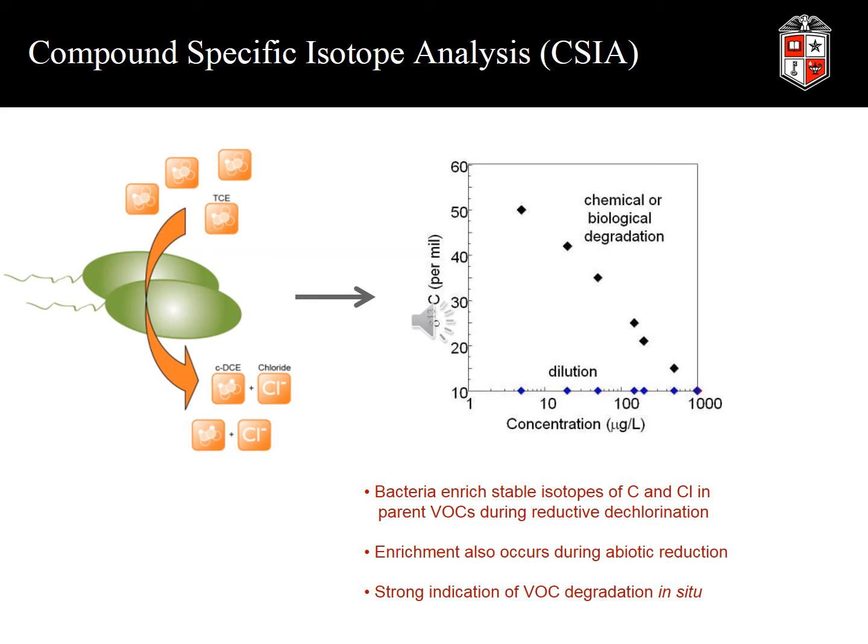Combining all these together gives you much more information about what occurs at each individual depth than you would otherwise be able to get unless you put in very, very high resolution wells, well screens every 1 foot. And even then, it's possible that if it was a low permeability region, some of the well screens would not return data because the sediment around it would have too low a flow rate to be able to sample by well.